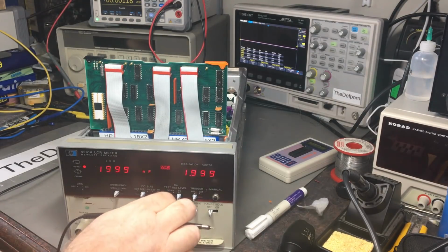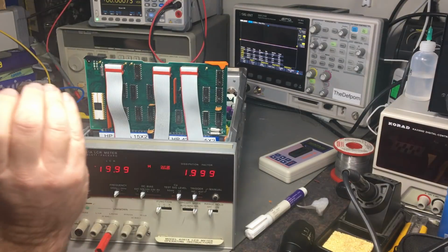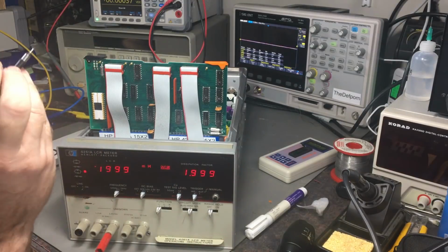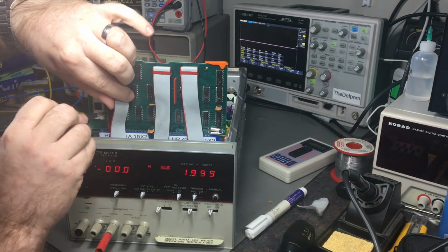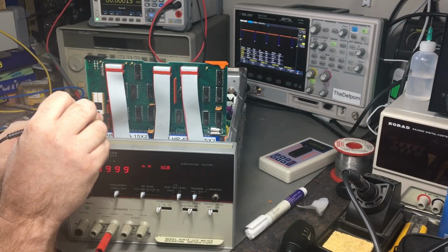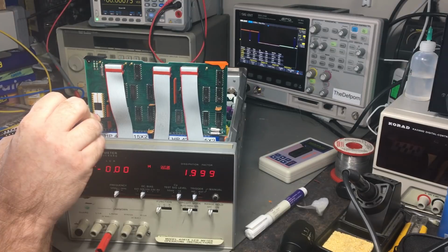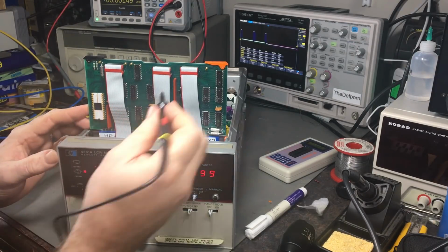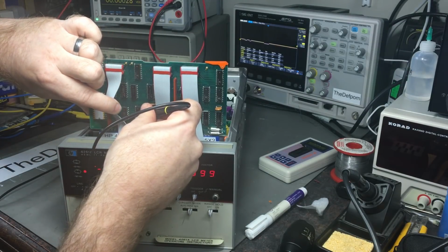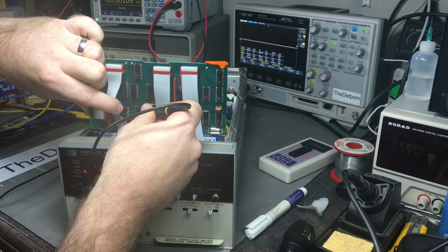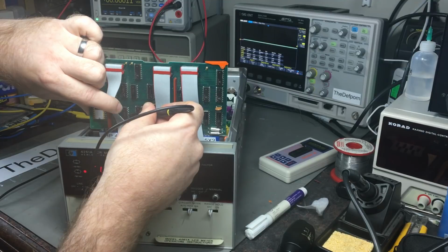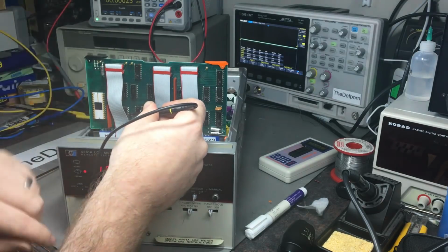So now to do inductance with an open. I'll do the same sequence again, so parallel. So do it again. Pin 4. Yep, that's pulsing. That's correct. Pin 6 should be pulsing. It is. Pin 8 and pin 10 should both be low. So 8. Yep. Pin 10. Yep, cool.